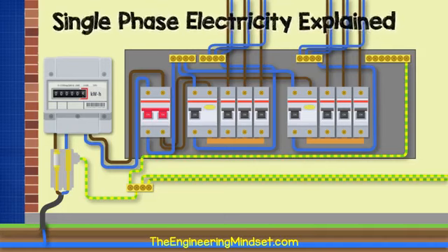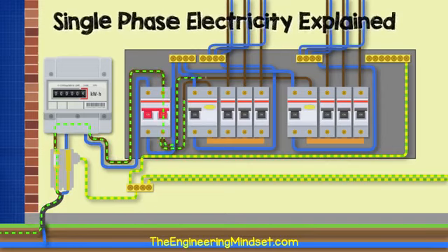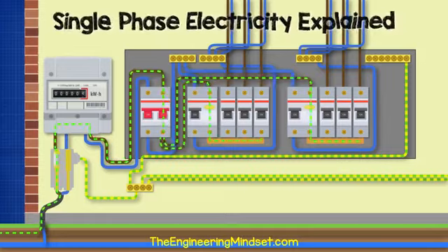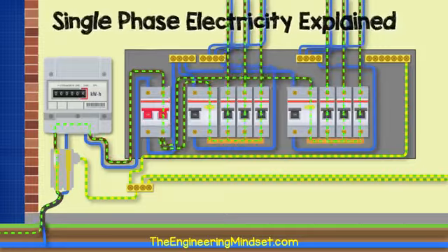So electricity can then flow from the main distribution phase line, up through the service head and the main fuse. It then flows through the electricity meter and into the consumer unit main switch. From the main switch it flows through the RCD, along the bus bar and into the MCB. It then flows up around the MCB separated circuits.